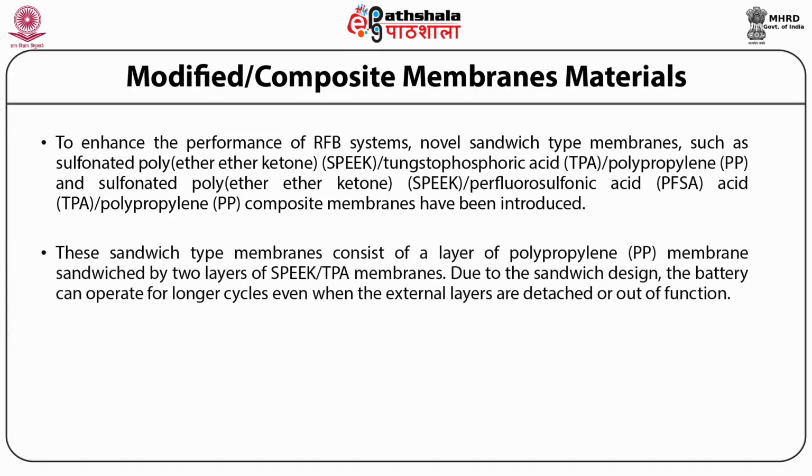These sandwich-type membranes consist of a layer of polypropylene membrane which is sandwiched by two layers of SPEEK or TPA membranes. Due to the sandwich design, the battery can operate for longer cycles even when the external layers are detached or out of function.